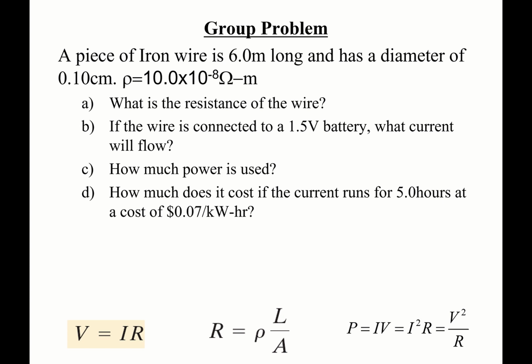Again, remember, put everything into meters, seconds, ohms for doing your calculations. When you do the last one where you're doing kilowatt hours, you need to put your power from part C into kilowatts and the time into hours to get the correct answer.